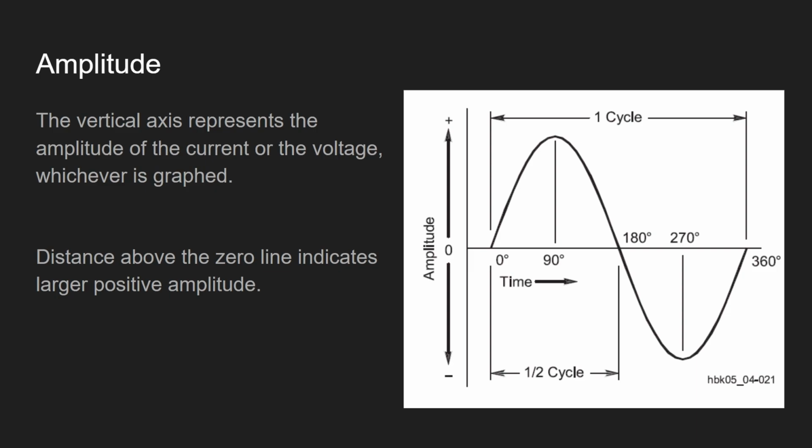What I mean is the sine wave may shift on the y-axis. It may shift higher or shift lower. So when you measure the amplitude, just measure the peak to peak. Oh no, it should be peak to peak divided by 2. Okay? Let me go through it once again.